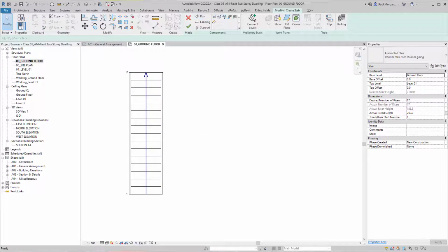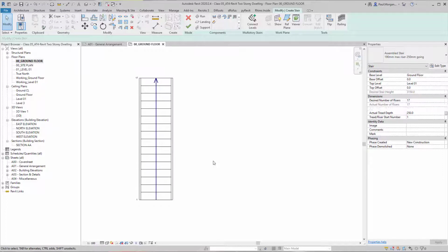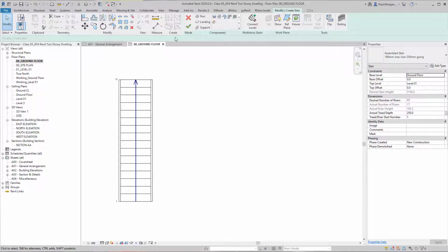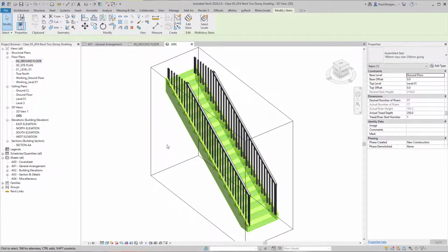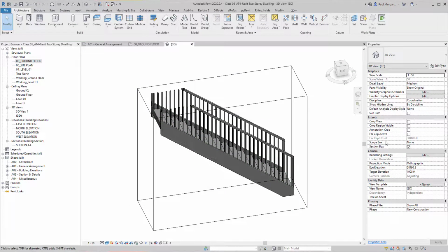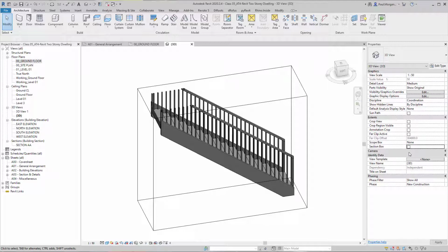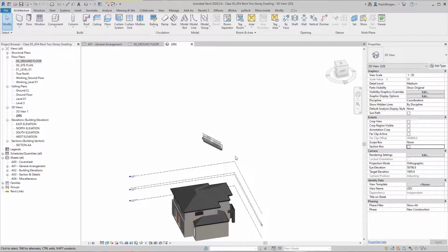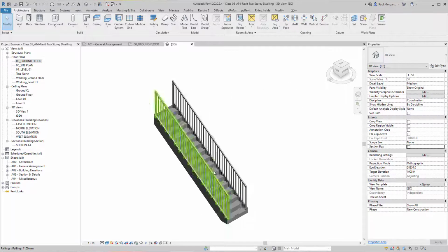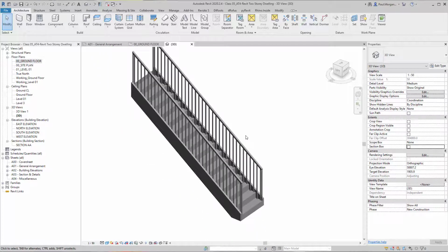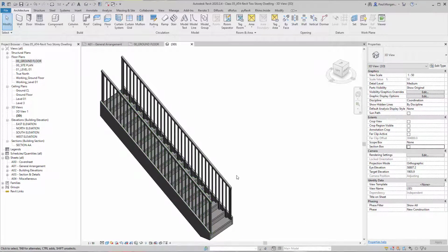So from here, let's take a look at this in 3D. I'll click OK, and it's going to look like this. I'm going to go BX for box to make a section box around our object. And then I'll just turn off the section box so it brings everything back. So I'm in our file, just drawing away from our house at the moment. This is just a standard assembled stair, and it's just one consistent run.